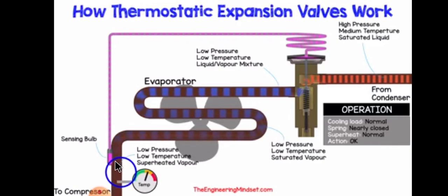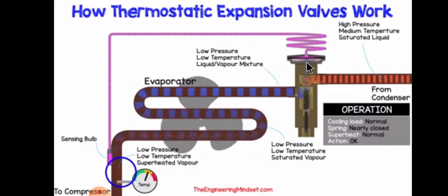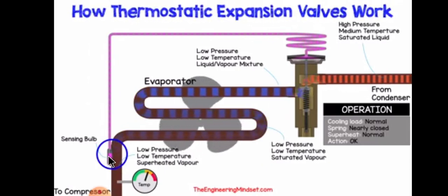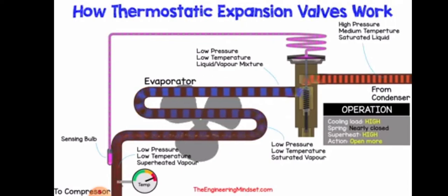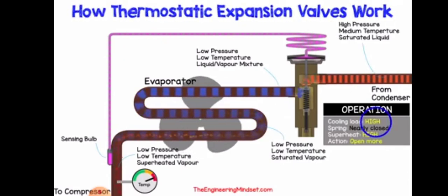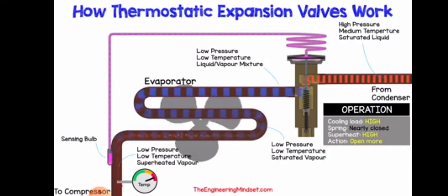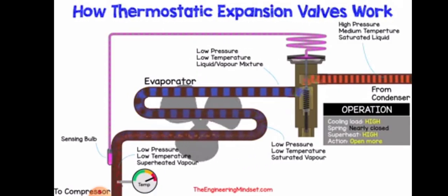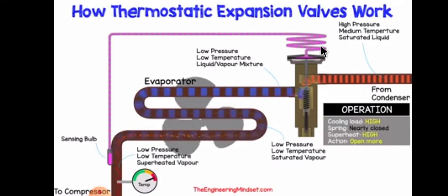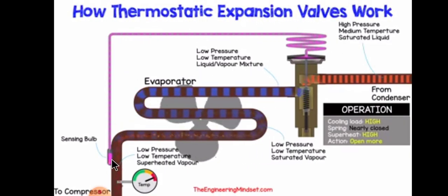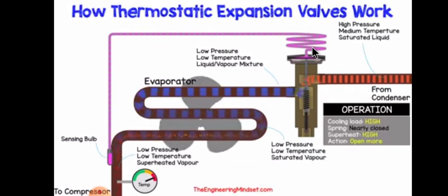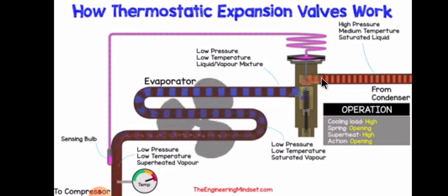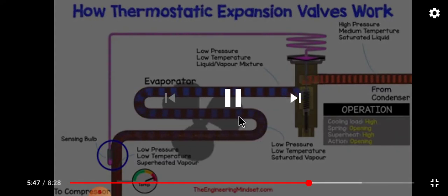If the evaporator temperature is higher, the expansion valve fully opens, and when it goes to the normal or set temperature, like if you set the temperature to 22, when the evaporator is not getting very high or not absorbing heat from the environment, the gases in the sensing bulb get lower temperature and pressure, so it closes down this valve and adjusts the flow of refrigerant.